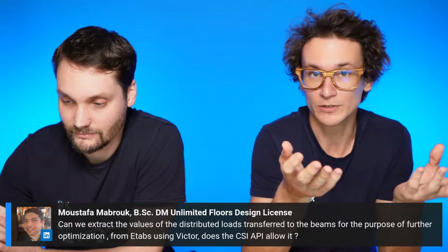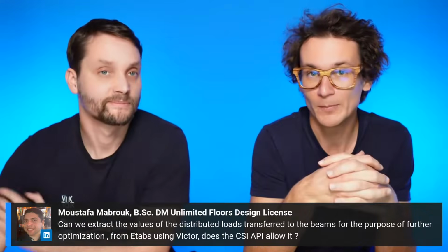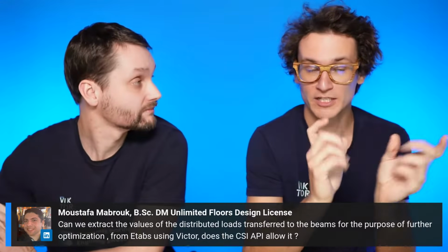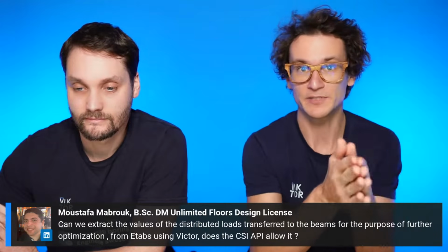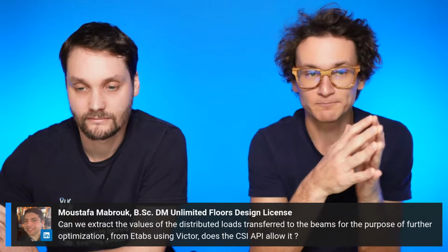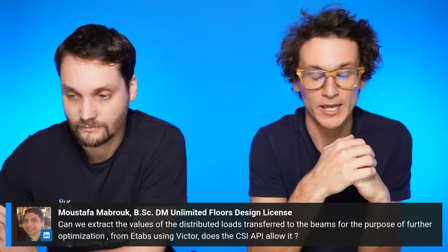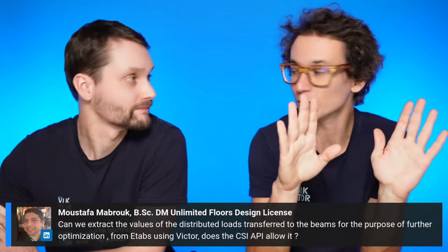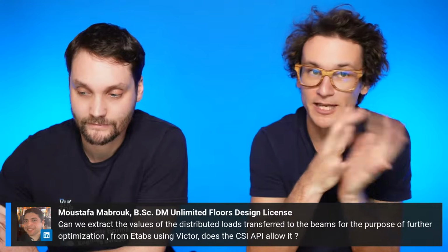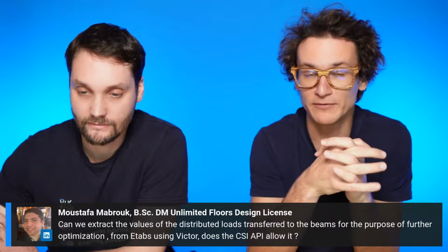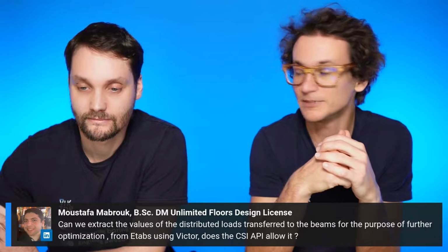So anything that you also see in the tables is pretty much available through the API, and you can do post-processing of that, if you've got specific checks that you do personally that ETABS can't do. For example, you can do many code compliance checks outside of ETABS. For example, if you've got a shear wall building and you want to check whether your spandrel rotation is compliant with the code, I don't believe ETABS does that at the moment. So it's quite a painful exercise, but all those checks can be done outside of ETABS with VIKTOR.